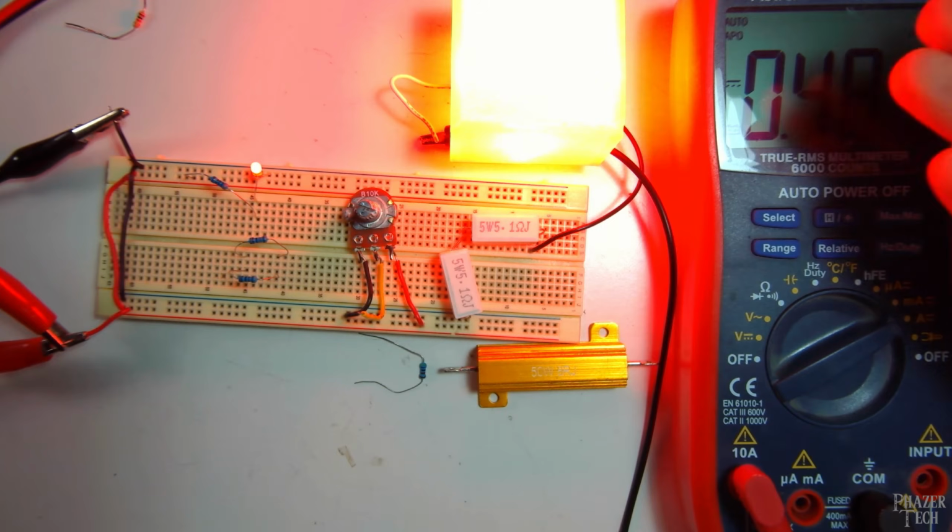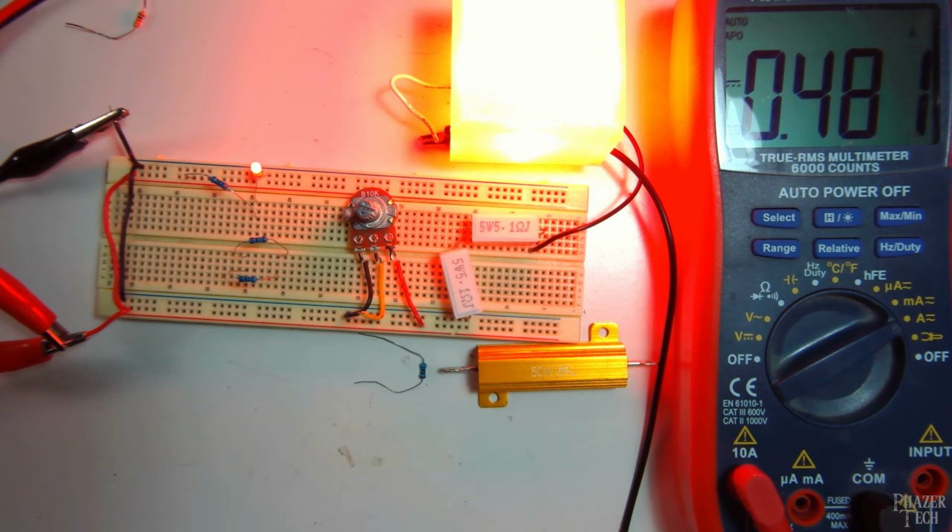But actually, we could get this LED a bit brighter if we used a slightly smaller resistor value. Not power rating, but ohms. Also, I realized after filming this that the forward voltage for this LED is higher than 1.9 volts. It's more like 2.1 volts at least, which explains why we're getting a lower than expected current draw given this resistor value. Also, the resistors themselves don't have perfect tolerance. They're going to be off by a bit, so that's why the reading is less than 700 milliamps. So hopefully now you have a better idea of how to use resistors to limit the current.